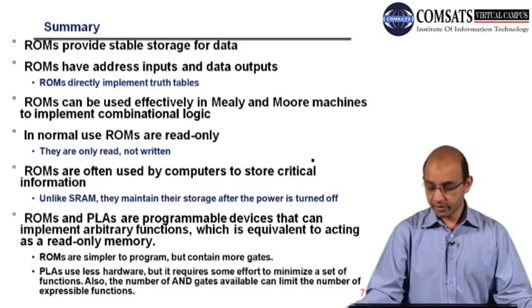Then we mentioned that those ROMs have the potential of being used in an effective and efficient way, and in order to achieve that, we need to replace the decoder, and we call this configuration PLAs, programmable logic arrays. With this configuration we can minimize the number of minterms generated by the decoder.